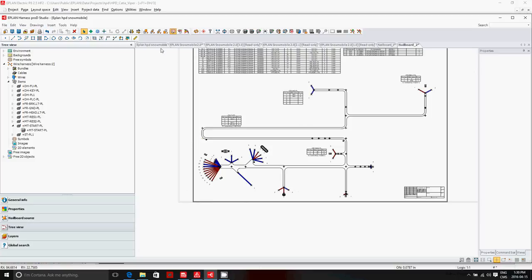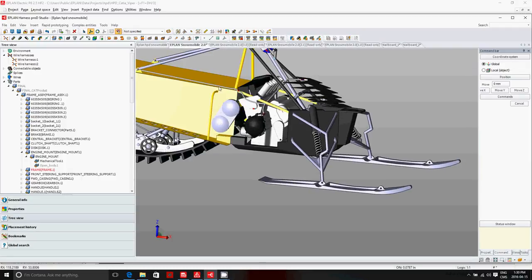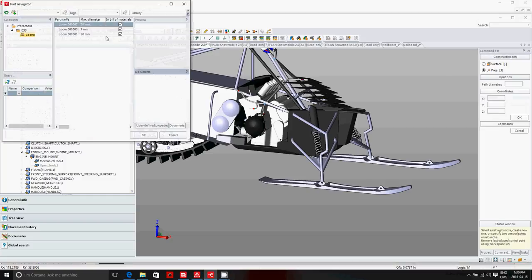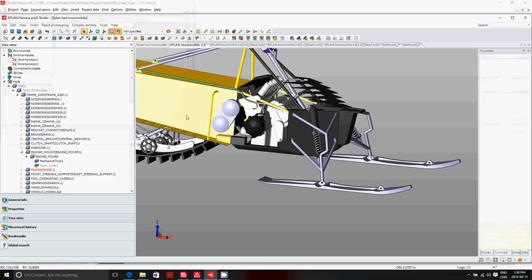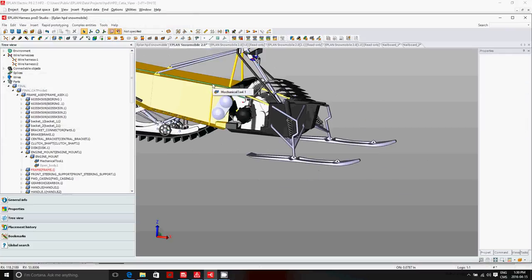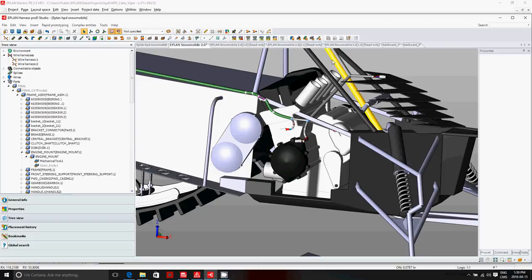You can, on the 3D model, now decide that you want to change, let's say, some of the surfaces. You can assign different surfaces, protection surfaces. We call them here wrap tapes or looms that you can place for each of these. So you just have to pick which one you want, and you just assign it to a specific one. The color, of course, changes. That's all controllable. And once this is changed, then of course on the nail board you'll see the reaction.